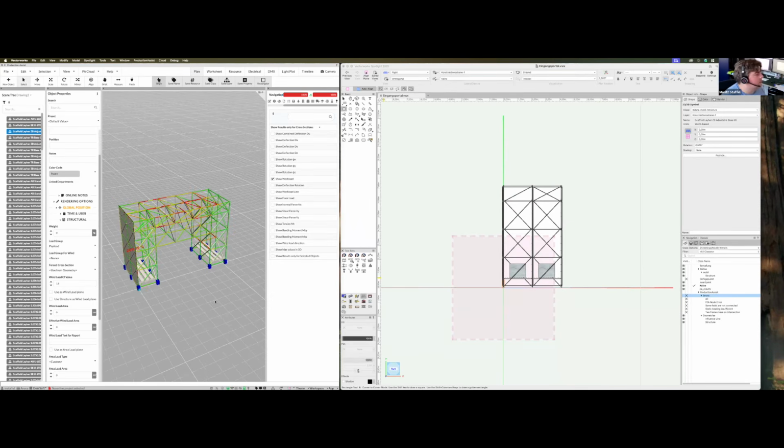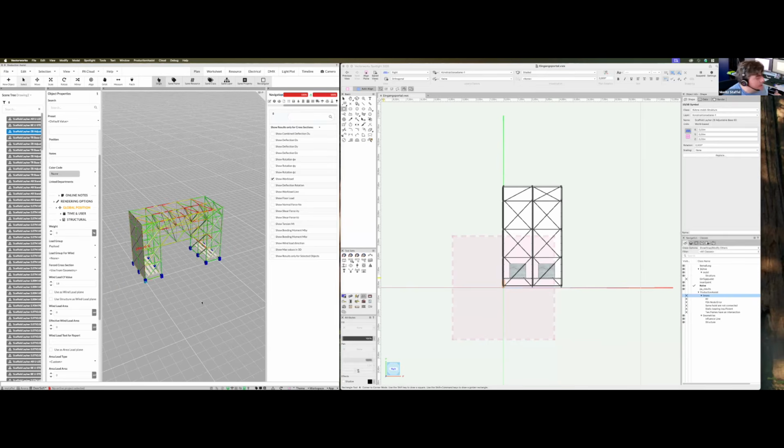So all the Vectorworks symbols are prepared. There are some special libraries that don't work so well, but with the next update we will have our own library that you can use for the calculation. An important thing, as we are now approaching the end of the layer scaffolding topic: ground support calculation with wind load is really challenging.